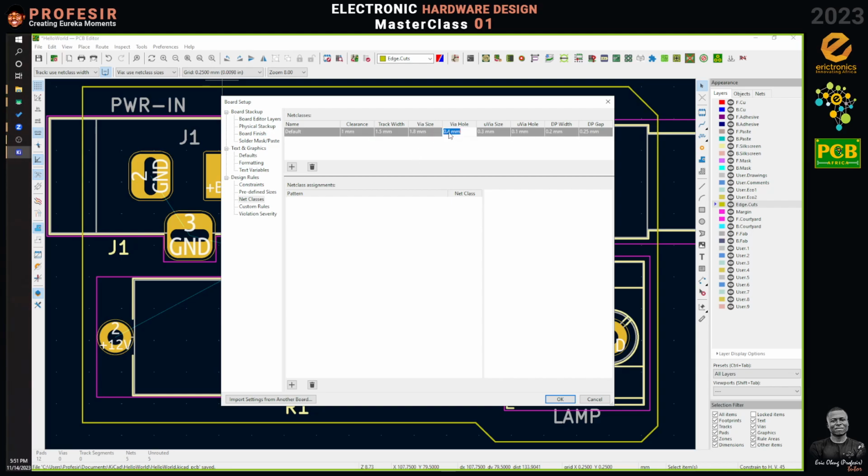And for the hole of the via, what I've seen is that it is very easy to get a 1 mm drill. Is that okay? Because after doing the work, you have to drill it. So if we make any via, we want the hole size to be as low as 1 mm. The rest of the things here, ignore them. We don't need it. Is that okay?